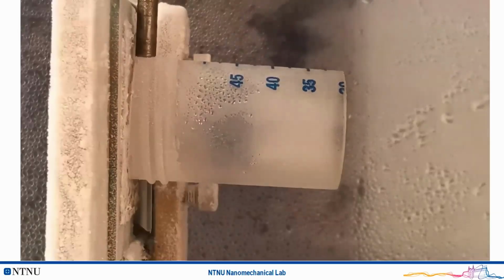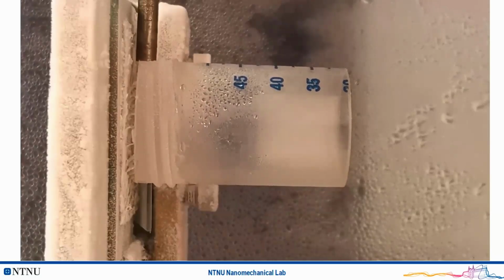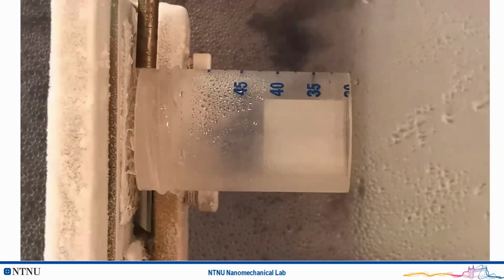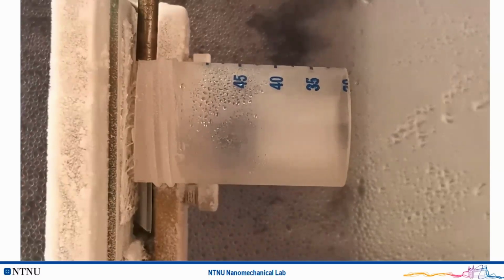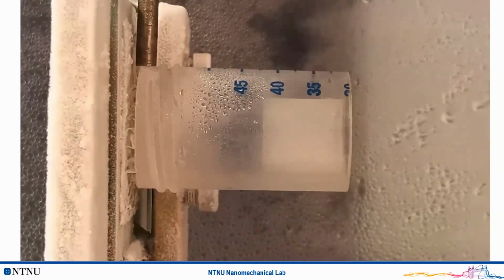I have a video to show how this sequential rupture happens at the interface. If we push this cube with the ice inside, you can see that those scales will actually rupture one by one, and they have the large deformation and then the separation of the ice from the substrate.